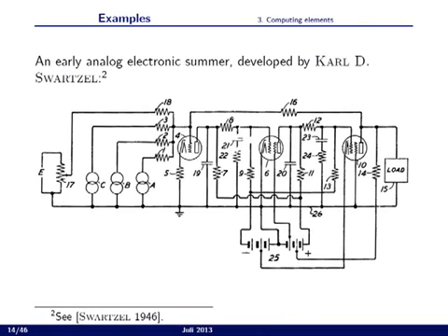You have several inputs, in this case 3 inputs for variable inputs and 1 input for a fixed input which can be set by a potentiometer, and you have a three-stage simple operational amplifier with a feedback resistor, and the load gets a voltage that corresponds to the sum of the input voltages and their respective currents.